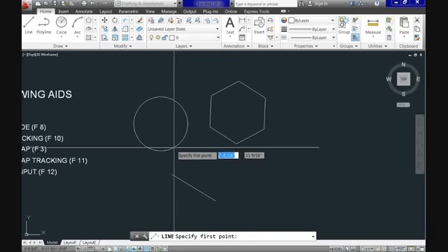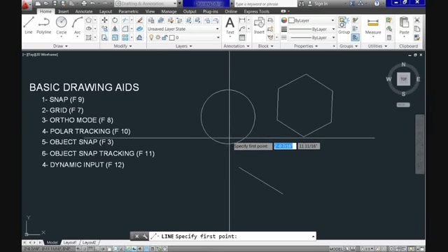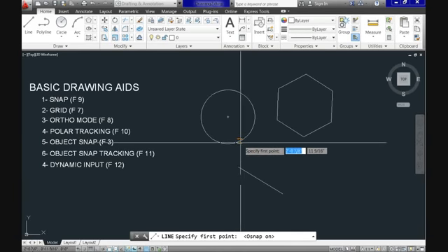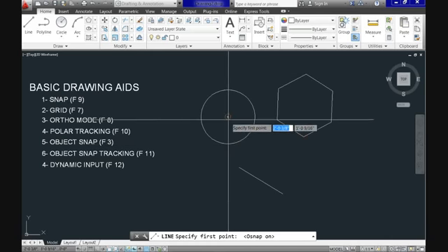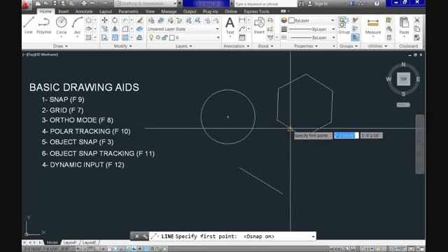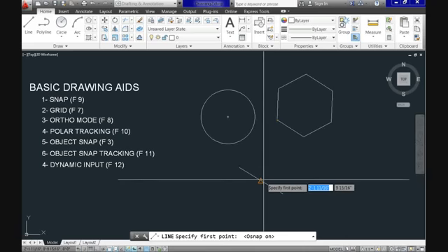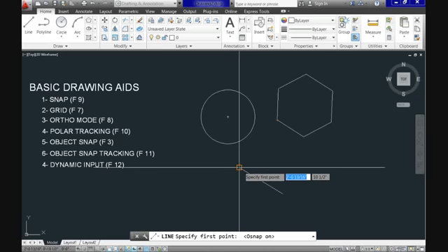When a command is active and you start hovering over some objects, you can see that some suggestions appear with markers like circles, squares, or triangles. Each shape has a specific meaning. For example, squares mean endpoints of lines or objects, while triangles mean middle or midpoints. Object snap is really helpful since it allows you to draw with extreme precision.